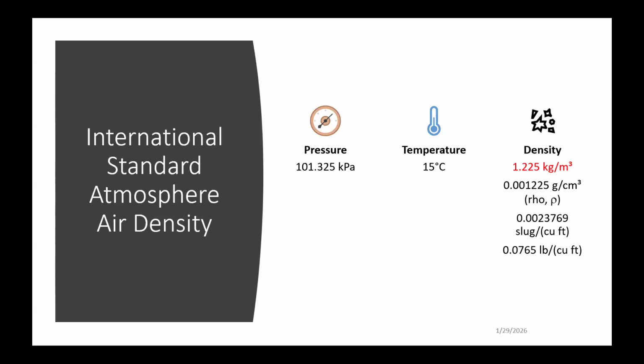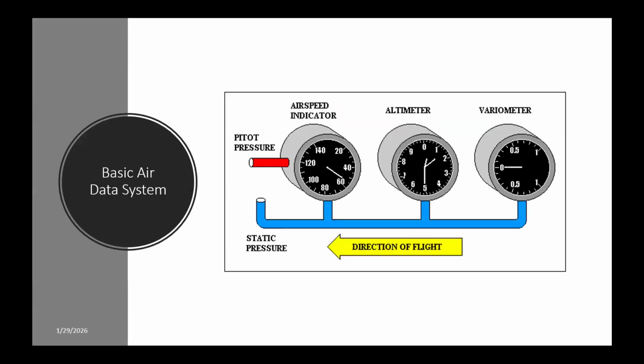Now, when you look at this, our sea level adjusted barometric pressure generally doesn't swing more than about 1.5 inches of mercury, plus or minus, or about 51 millibars, or about 5.1 kilopascals. Having a high pressure move in or a low move in can drive the barometric pressure up and down. But the thing that's really driving the density altitude is going to be temperature. That's the one that really drives the number change for the density altitude.